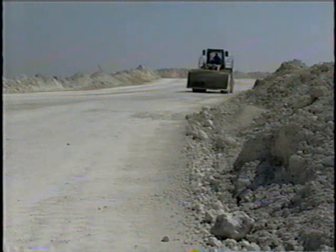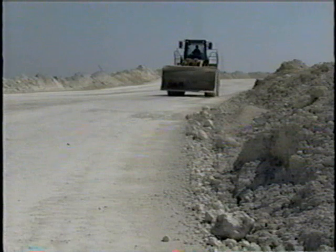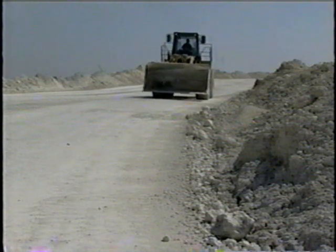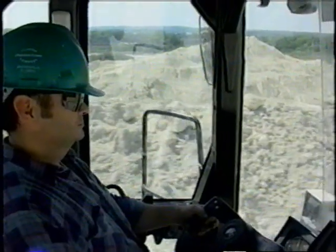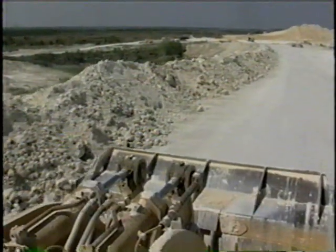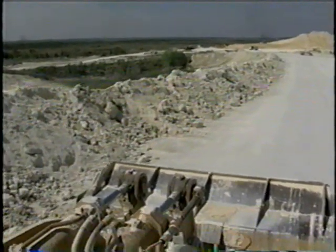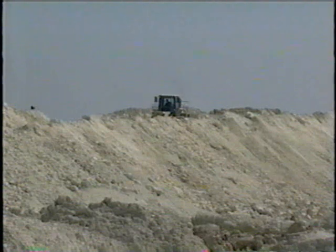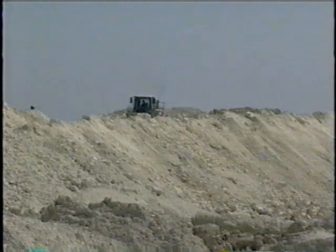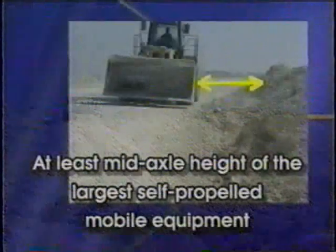One final area of hazards and safety needs to be covered with the operation of mobile equipment. Equipment travels on roads in the mine, sometimes with steep grades on either edge of the roadway. Berms or guardrails shall be provided and maintained on the banks of the roadways where a drop-off exists of sufficient grade or depth to cause a vehicle to overturn or endanger persons in the equipment.